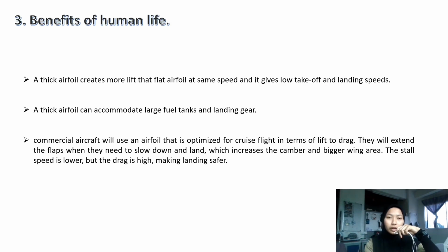The benefit of airfoils in human life: a thick airfoil creates more lift than a flat airfoil at the same speed, and it gives low takeoff and landing speeds. A thick airfoil can accommodate large fuel tanks and landing gear, and for commercial aircraft we use an airfoil that is optimized for cruise flight in terms of lift to drag.